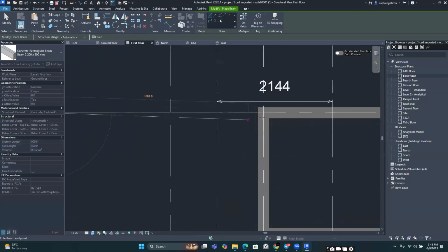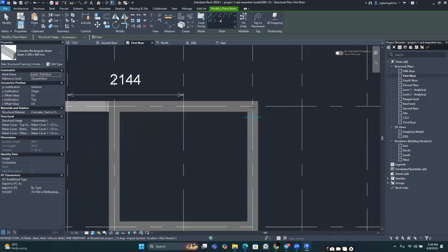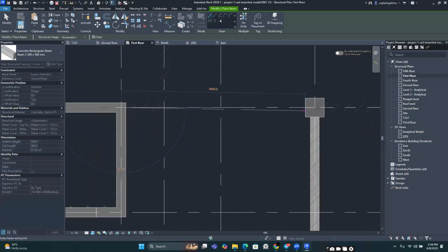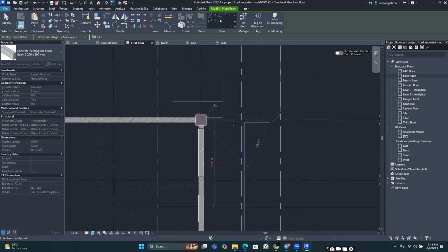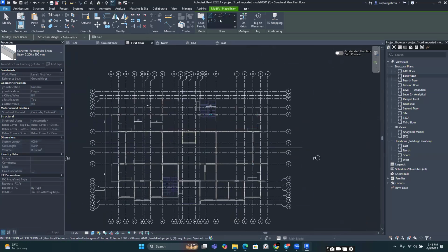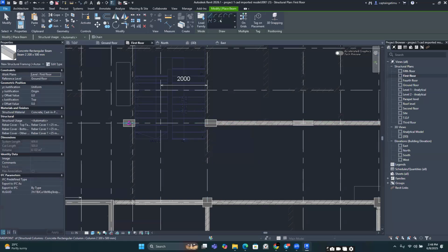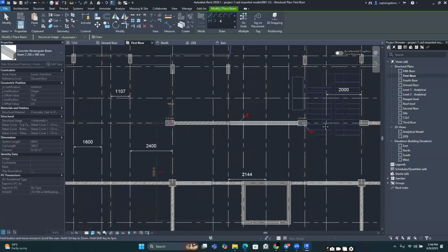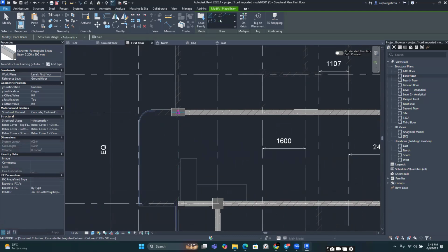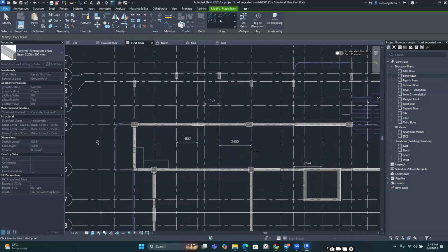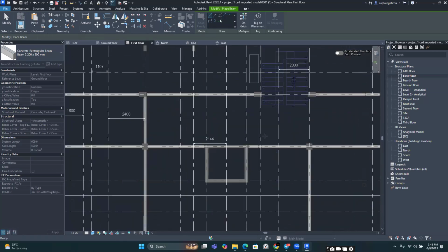And then here the shear wall, don't draw the beam through the entire shear wall, just end it at this section here, press escape, and then continue from this other end. And then click on this point there, at this point here, and end it here. Okay, and then do the same here. Here you don't need a beam over the staircase, then here, and here, and you're good to go. So I'll just model those few beams, and then I'll expect you to model all the other beams. Okay.